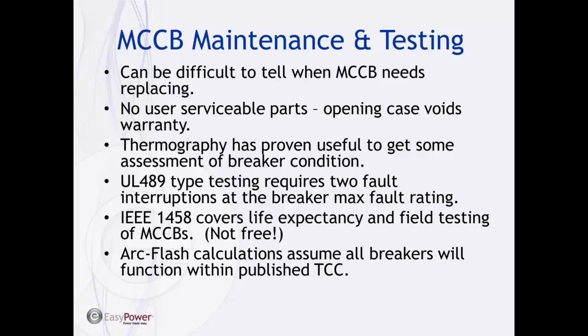And again, all the Arc-Flash calculations that we do assume that all the molded case circuit breakers are going to work per their published time current curves. So that puts a little more emphasis and importance on making sure these breakers are actually going to work when they need to work.